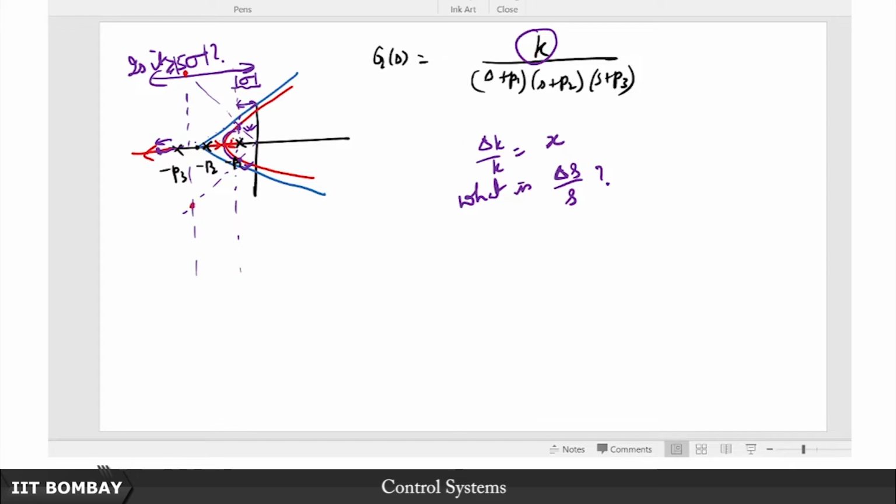So one quick idea is, if you want to shift the root locus here, we've seen earlier that for a second order system, the addition of a 0 on the left half plane has the effect of moving the overall root locus to the left. Now we wonder, is the same true of a third order system or higher order system? Let us try to find that answer.